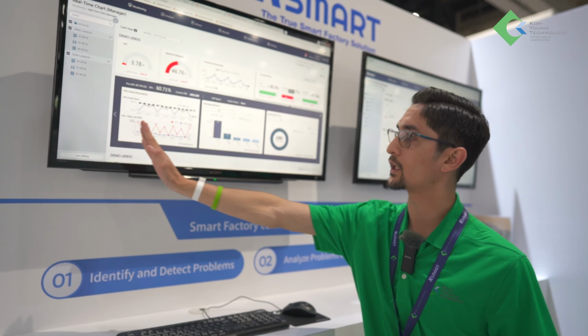So now going back, apart from the summary of the inspections, we have very capable systems or solutions for connectivity between machines. So we have what we call the 3-point view or link system, which will give you detailed information about the entire process, from the SPI on the printer, the mounting process on the pick and place, and the reflow process after the oven. All these pictures are synchronized so that you can understand the result of the entire process of the line. So your solder paste being good, your placement not being good, and your reflow being good. This can tell you root causes in one single snapshot.